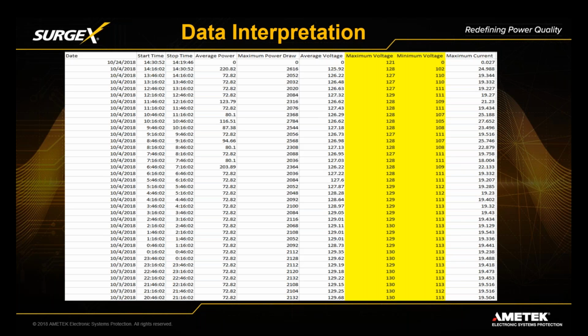I talk to dealers for sure, and about every day to every 3 days we get another new enVision log to look at. I've started collecting these enVision logs for the past year and a half roughly. We have well over 100 dealers' worth of enVision data from all over the country. And the one thing, I just mentioned this in a dealer meeting near Seattle yesterday, the one thing that I'm noticing as more and more of these logs come in from all over the US, the instability of the grid is definitely something that our customers seem to be beholden to. And it's the fluctuation in voltage that I find seems to be the biggest nuisance.